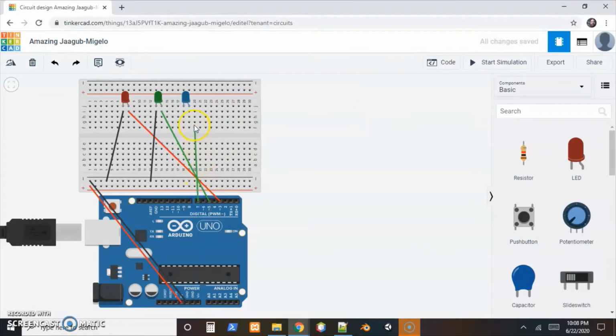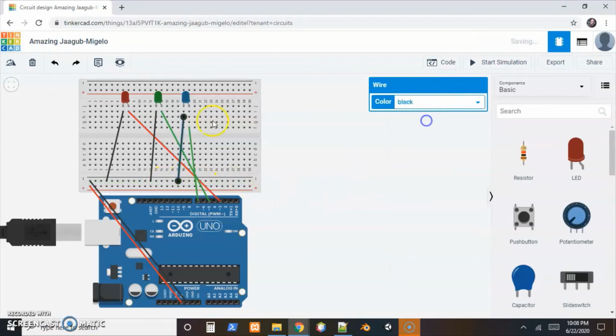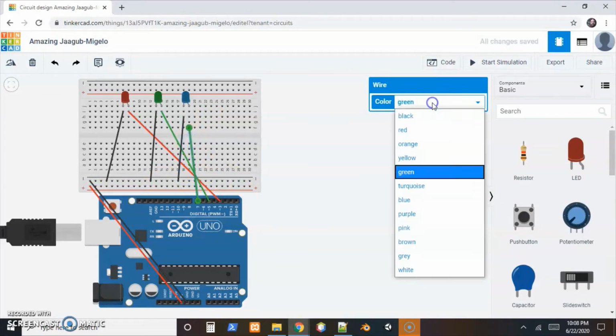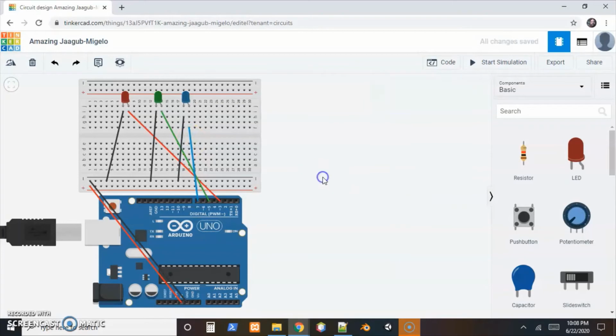So for this, let's bring pin 7. We'll use that to bring the source in. And I'm going to come to a different row here, just to accentuate the point that all 5 of those are connected. So all I have to do is bring the 5 volt, the high voltage to that row, and it'll go into the LED. And then flow over to this other row, and then just any of these, I'll bring it back to any of these in the ground rail. Change that wire to black, and click on this, and let's make that blue, that way the wires match.